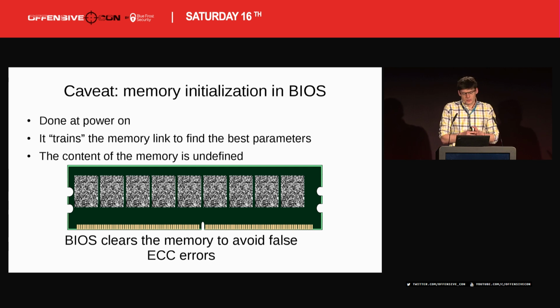Because the memory initially has, let's say, random data, so you cannot make an assumption there. This random data is also valid for all the chips, including the control bits, so you cannot start reading the memory without getting ECC errors. So any machine with ECC memory will first try to clear out the memory, or try to write something to it.